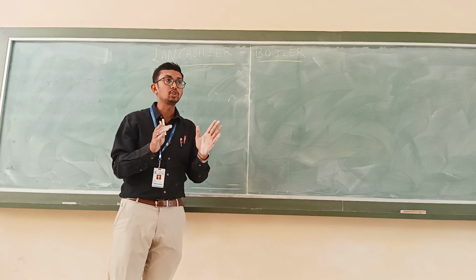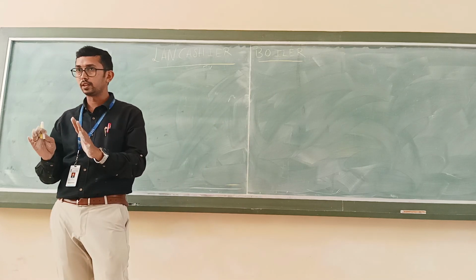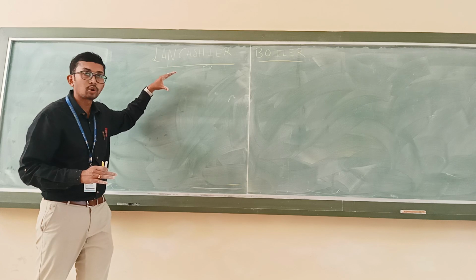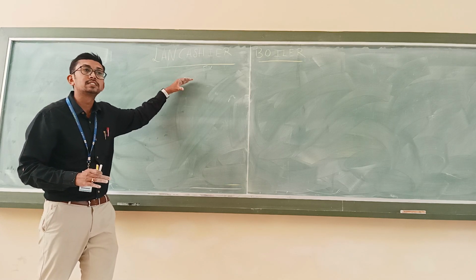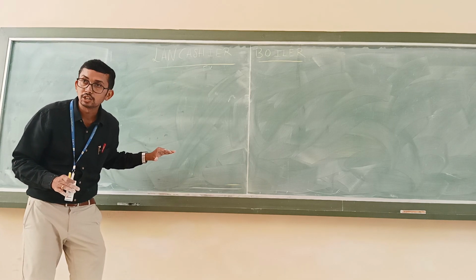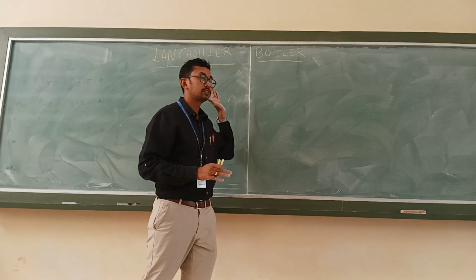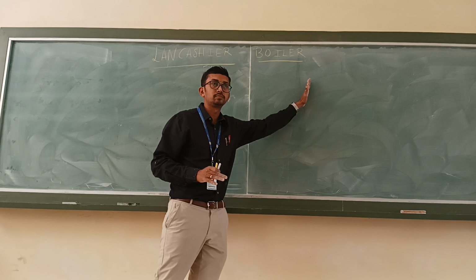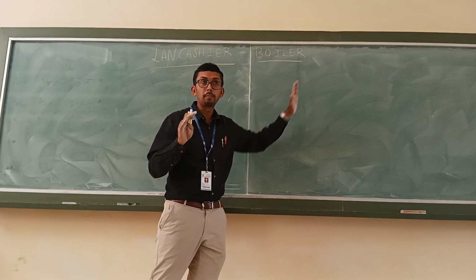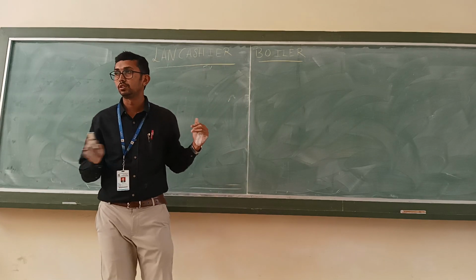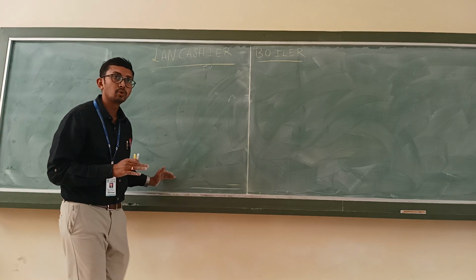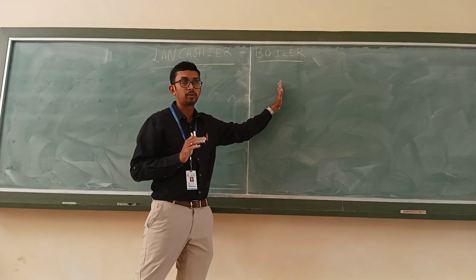So while writing, you have to plan in such a way that first you are going to write the front view. Exactly below you have to write the top view. Exactly to the right side or to the left side we have to write the side view. So that is the proper way of writing this sketch: front view, top view and side view in a proper way.